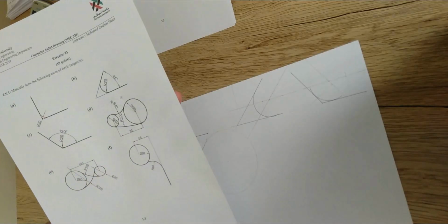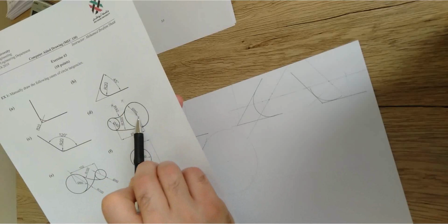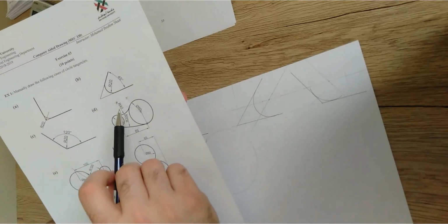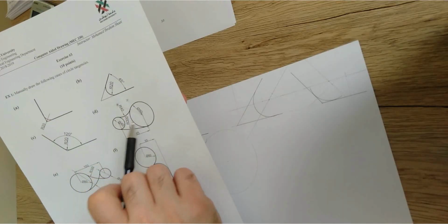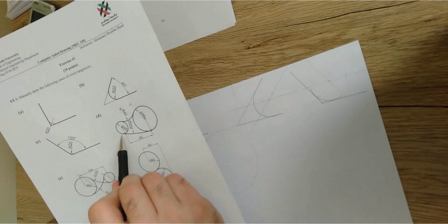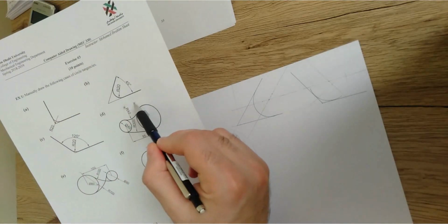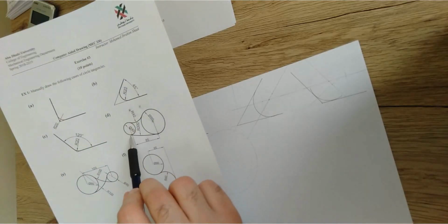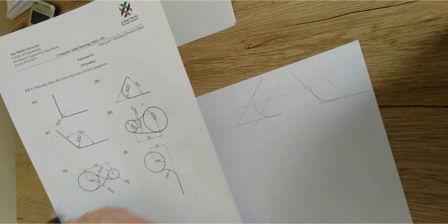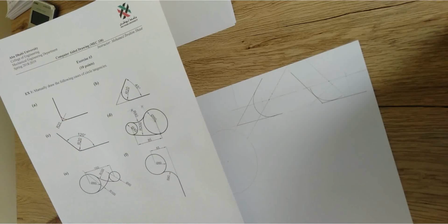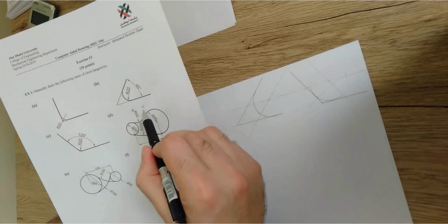Very simple. If we're gonna go over the tangent point while moving from the center to the center, it should be addition. If we will not move over the tangent point while moving from the center to the center, this should be subtraction. The same thing from the other side. If you try to move from the center of this curve to the center of the small circle, we will not move over the tangent point. The tangent point is far from the path from the center to the center. So what does it mean? It means that we have to subtract.